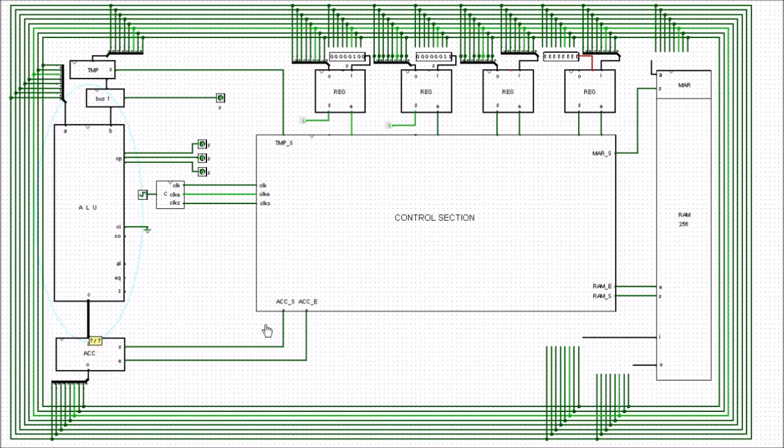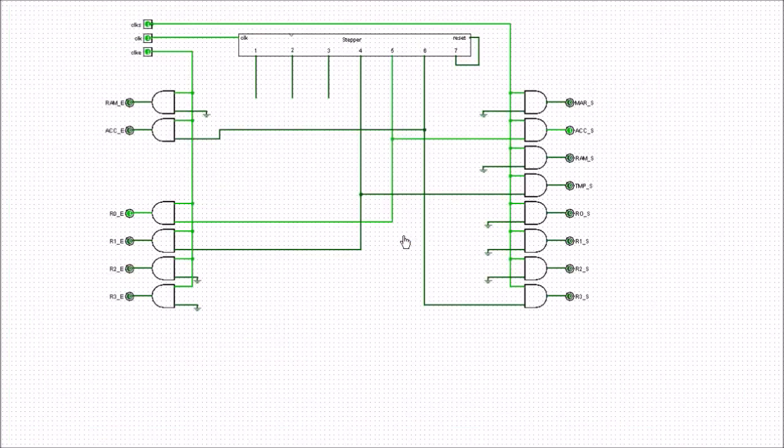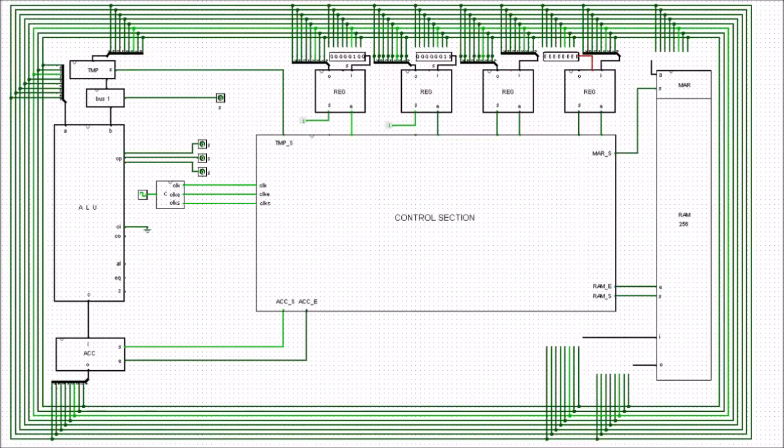It's not going to get into the accumulator until we set the accumulator, so we can do that with the next clock pulse. So whenever the set goes high, you see here, the accumulator now has been set, so we've now got that information, number 7, in the accumulator. So now we're ready to go on to the next step, which is step 6. So again, the set goes low, so that's information stored in the accumulator, and the enable goes low, and then the next clock pulse, the enable is going to go high.